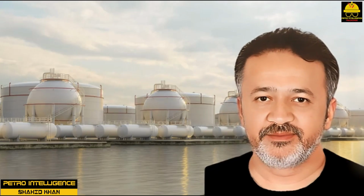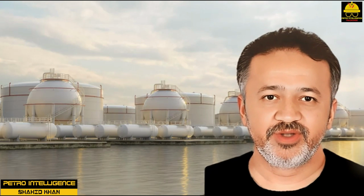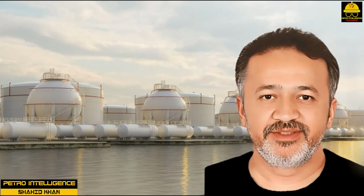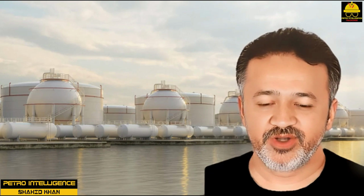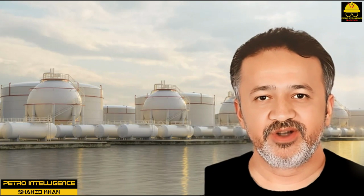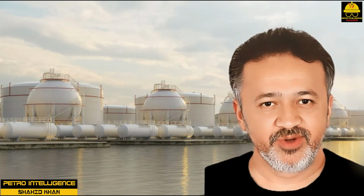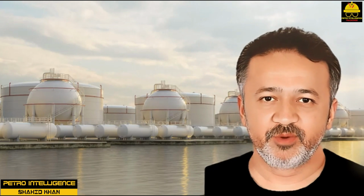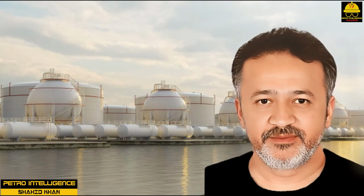Pressure tanks. Pressure storage tanks are used to store volatile liquids, which have a Reid vapor pressure greater than 18 pounds per square inch, psi. There are three types of pressure storage vessels: drums, spheres, and spheroids. Drums are cylindrical vessels with ellipsoidal or hemispherical ends built to withstand a given internal pressure.